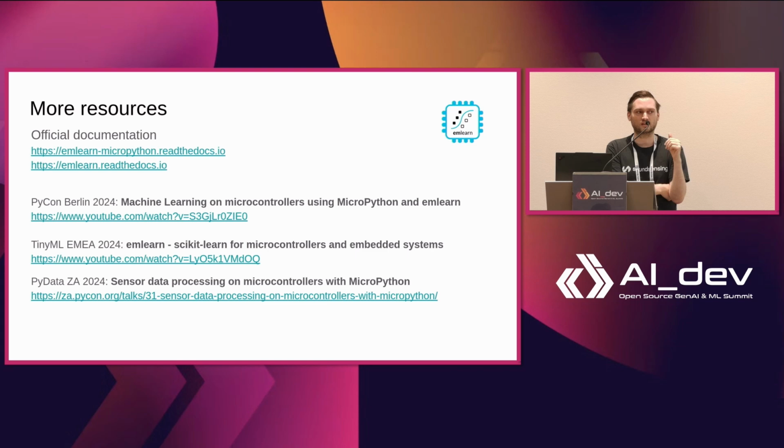Yes. The question is, there was one example shown with more like object detection of a cat. Is that doable on the microcontroller grade, or where does it typically become a limit to where you want to go to a bigger system? So yeah, you can. I think for the smart doorbell, you probably don't need object recognition. If you position it well, you design it well, like you have a cat hatch or something, you could just do all the image classification. That would work super well. You don't need high frame rate or super high resolution to recognize a cat.